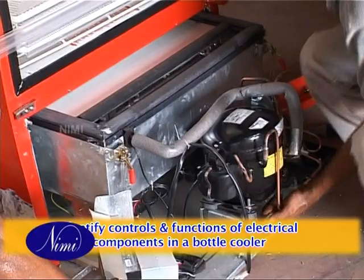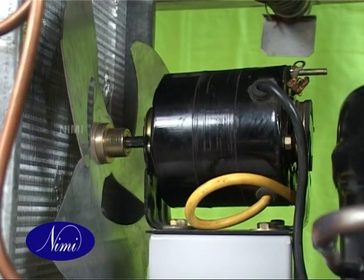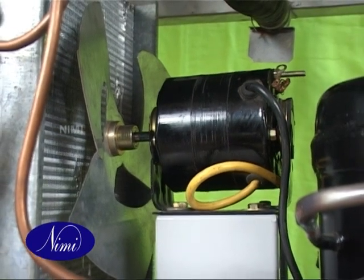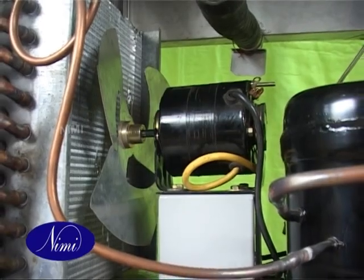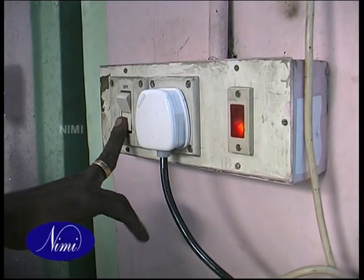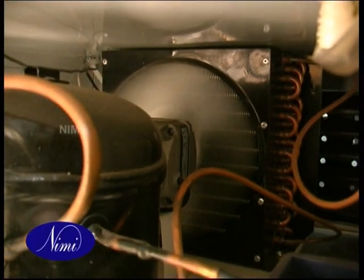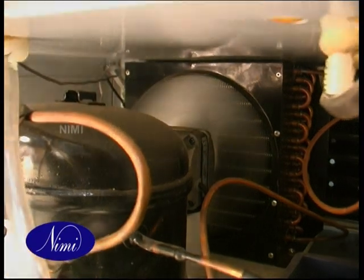Identify controls and functions of electrical components in a bottle cooler. Fan motor. Locate the fan motor attached to the condenser in the condensing unit of the bottle cooler. Switch on the bottle cooler and understand that the fan motor serves to cool down the condenser coil carrying high temperature and high pressure refrigerant.